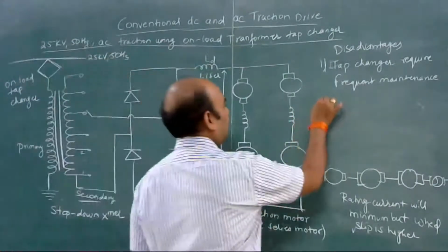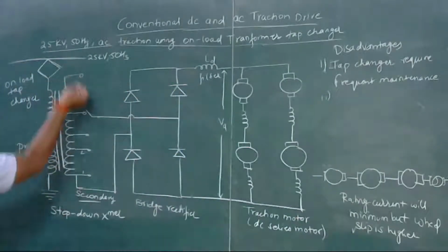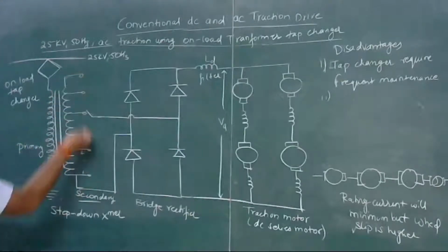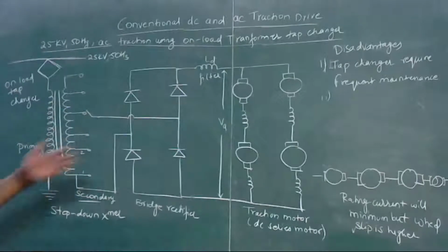Okay, and second, there is no smooth control in the speed. We have to change the taps, so there is a distinct step in speed control.